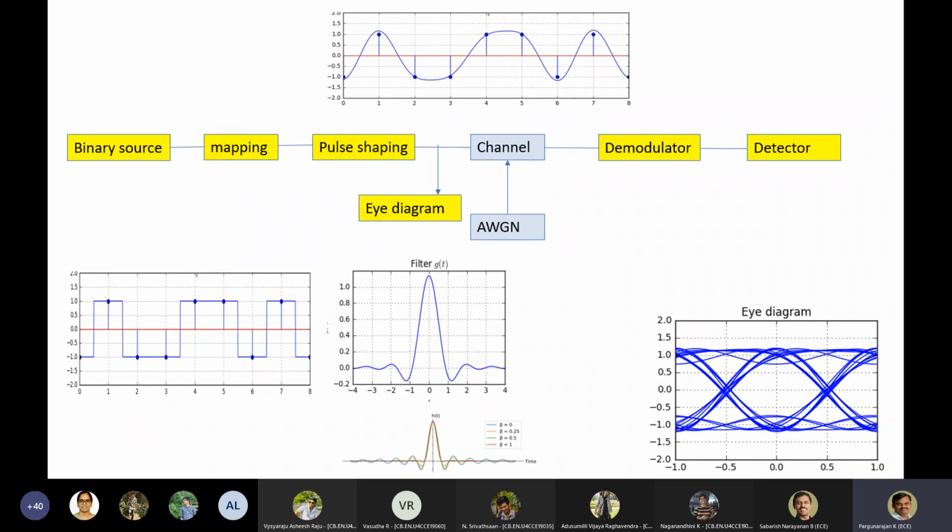We studied PAM, binary PAM, M-ary PAM, PWM, and we studied some line coding techniques. All these things we used to convert zeros and ones to some electrically varying representation. The reason is that the channel we have is a continuous channel; we can't give zeros and ones as such to the channel. So once again, binary zeros and ones we are converting to a time-varying representation, either with a line coding technique or with some baseband modulation. That is the thing I simply drew as a mapping here.